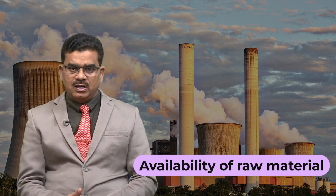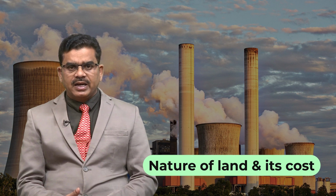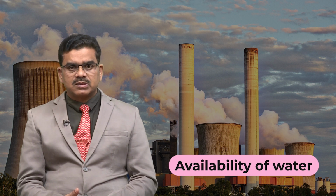Number one, we can consider the availability of raw material. Once the raw material is available nearby, the site can be selected for the steam power plant. Next is the nature of land and its cost. On the basis of the nature of land and its cost, we will select the site for a steam power plant. And the next one is availability of water, because water plays a very important role during the production of energy in a steam power plant. So, easy availability of water should be there.